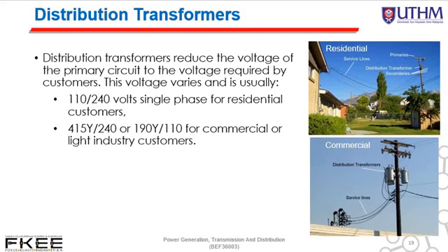So how to protect it? Normally a substation transformer has a minimum of 3 protections. The first one is secondary overcurrent relaying, the second one is primary fusing, and the third one is protection by a sudden pressure relay. Apart from that, transformers are also equipped with differential relaying plus a backup overcurrent relaying.